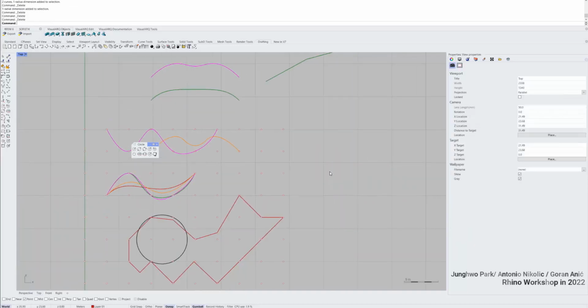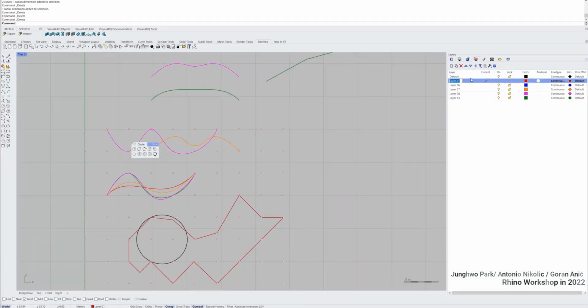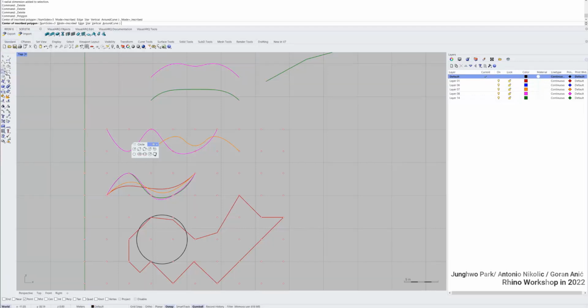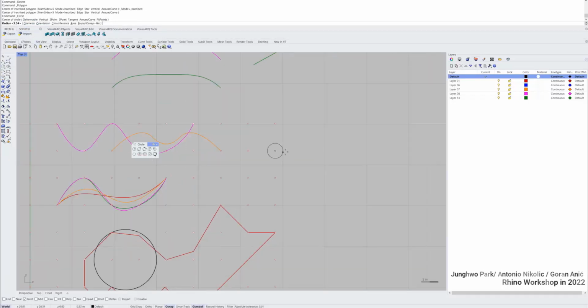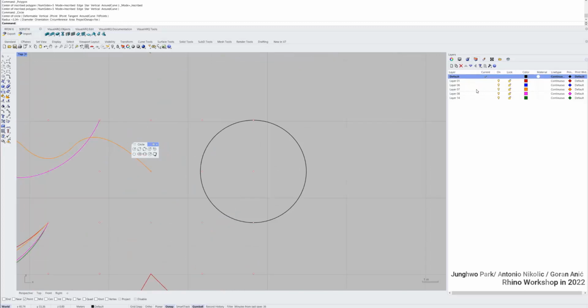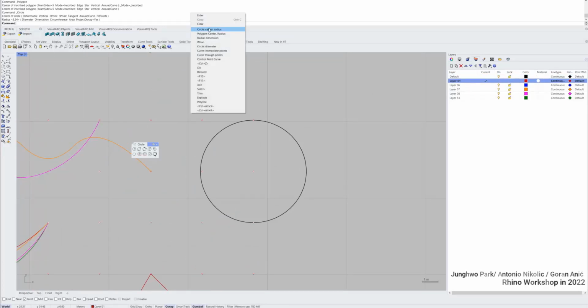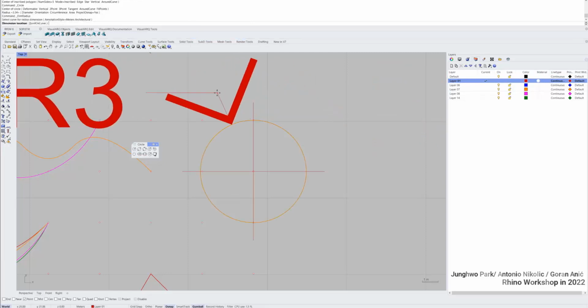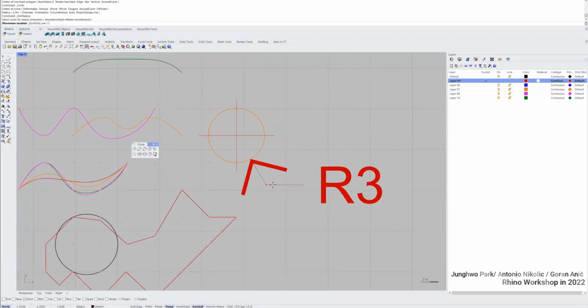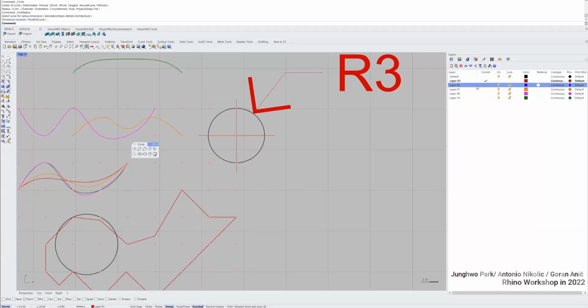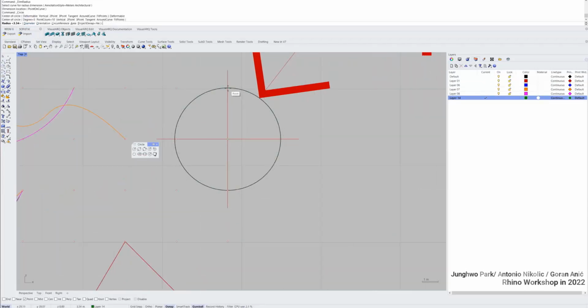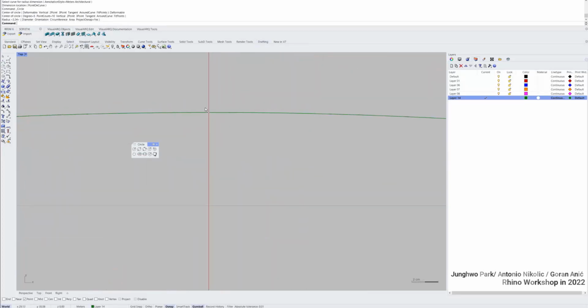So delete. Let's start with the first one, which is the normal circle, the standard circle command. I'm just using circle right now. The center of the circle is here, and we finish here. And when I use radial dimension now, you see the radius is the same. That's just a circle. But now let's compare with the deformable option of circle. There is deformable, and degree 5 we put it, and I'm going to select exactly the same endpoint here.